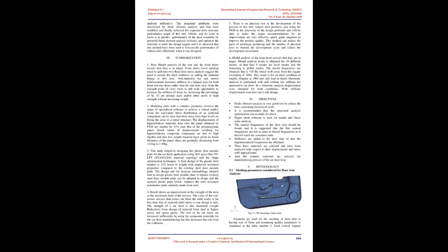Ductile: mild steel fails at the plane inclined 45 degrees to the axis of loading. Normal stresses cannot act on this plane and the only other possibility is shear stress. Out of different theories of failure, maximum shear stress and von Mises stress are based on shear stress. Von Mises stress gives a better correlation with experimental results and hence is preferred for ductile materials. Max shear stress is sometimes preferred over von Mises stress for designing rotating components such as turbine blade and compressor components.